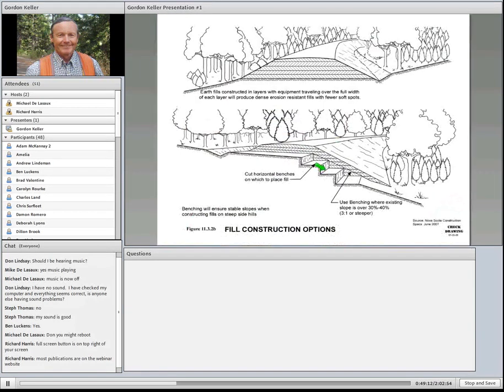Here you can see kind of what is ideally recommended for a fill slope. If it's very flat terrain, not a big fill, you probably don't have to worry about compaction. But if it is a very big fill, you want to get good subgrade strength, it's good to put it down in layers, maybe 6 to 12-inch layers, and compact it. And again, if you're on steeper slopes, you don't want to have a failure right along that organic layer or the contact of the fill and the old native soil. So you try and build in terraces. Costs more initially, but much better insurance against instability problems of fills.